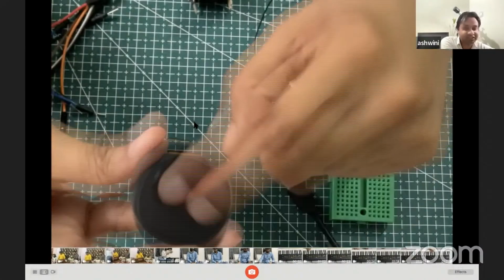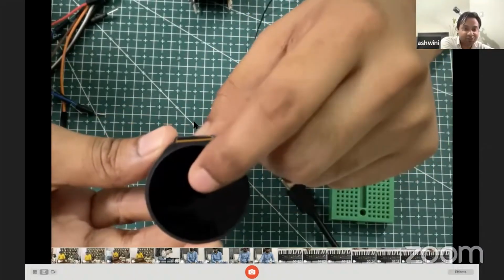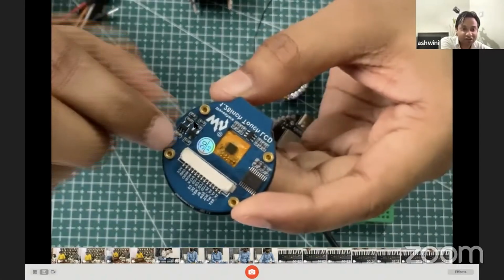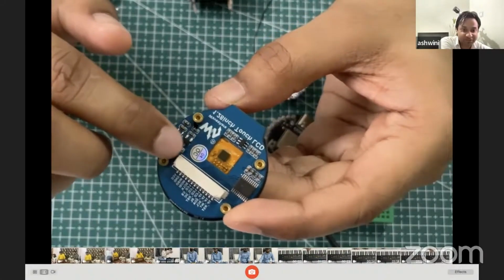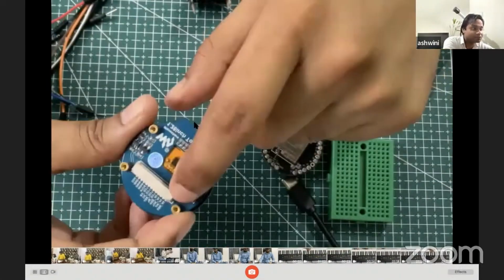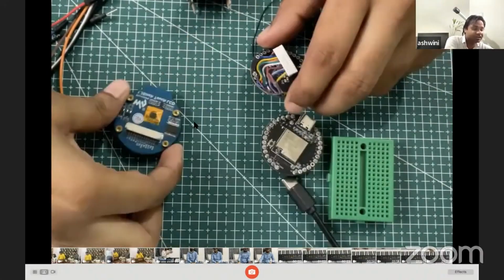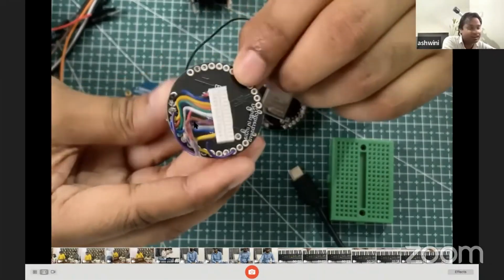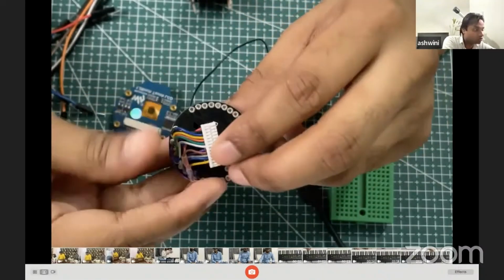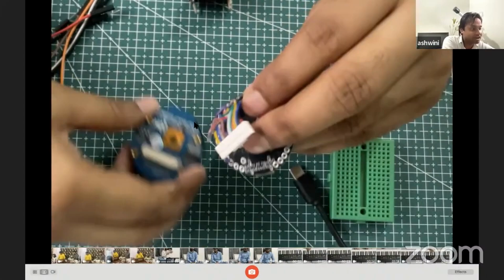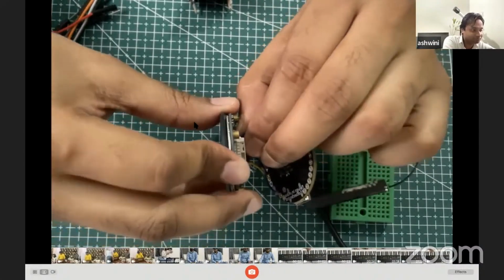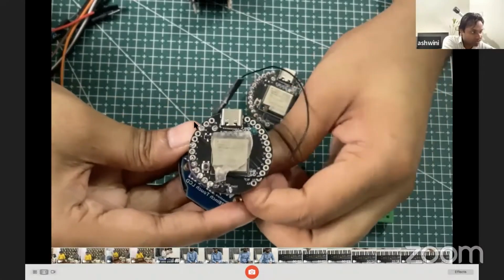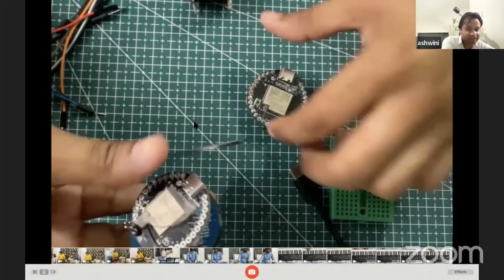And then we have the touch. We have the touch panel above the display. That touch panel works on the I2C interface, so it has the I2C pins, that is the SDA and SCL pins. I have soldered all these pins on the Indus board, like this, to access the display. After this, when I connect this, our display will be on, and I will be able to interface the display. This is how we will connect the display with the Indus board.